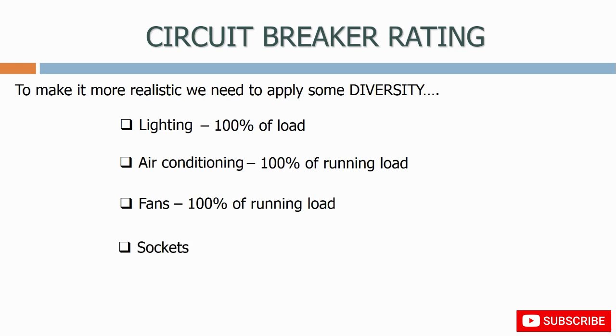And finally, what about the sockets? Is it likely that all the sockets will be fully loaded and drawing 8 amps from the system all the time? No, of course not. The socket load depends on what's plugged in, but it's very unlikely that all the sockets will be fully loaded. Therefore we apply some diversity. A common diversity principle we apply is to use 100% of the first socket rating and 40% of the rest. Let's now use this diversity factor in our previous equation.